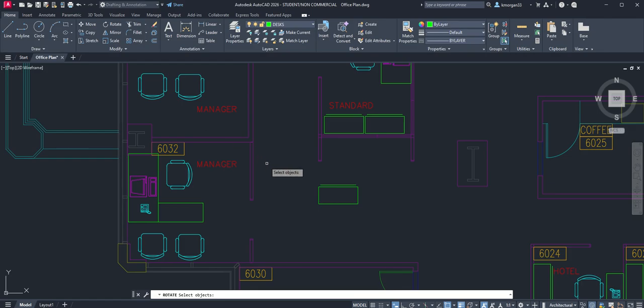I'm just going to go slow so you can see it. So rotate, select object, see inside the command line? Make sure that you are in the rotate mode by checking there's a little tiny square cursor. If you still have a positive cursor, then you're not in the rotate mode at all. Then we want to rotate this thing, so we select it. After you select it, make sure you press enter. If you forget to enter, you're gonna go into a different mode again.